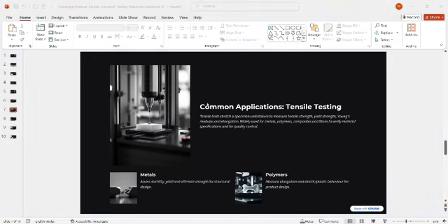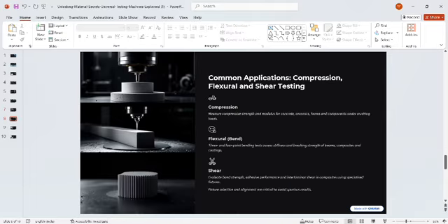If we fix our specimen here and apply tension, which makes it elongate, we can measure the tensile strength, yield strength, Young's modulus, and the elongation, how much it elongates. Likewise, if we stretch a specimen till failure, we can measure these properties, which is widely used for metals, polymers, composites, and fibers, etc.